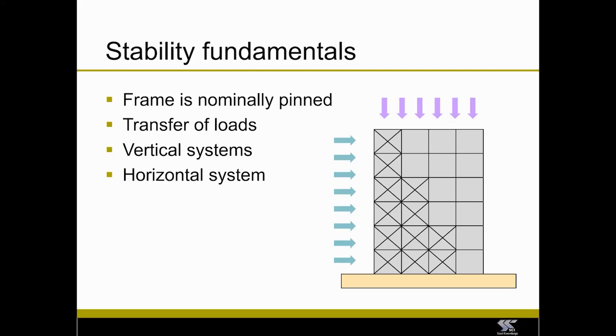But in this diagram, we've got that indicated with some diagonal cross bracing. The diagram itself doesn't show all the verticals that you'd find in a light steel frame. As we saw earlier, you'd have verticals at every 600 millimeter centers, so a lot more than shown in this diagram, but it indicates the purpose for what we need it for.